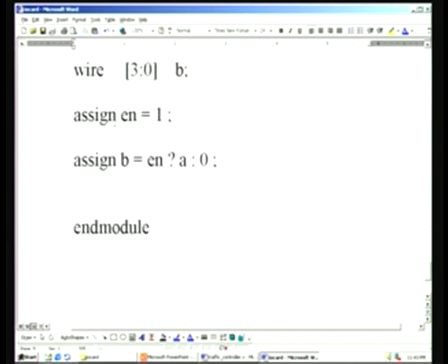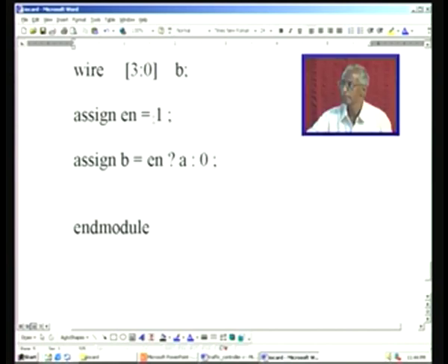So, for example, we enable first here, and in a concurrent statement there is another mux here. This is the output assigned: output B is derived either from the actual DIP switch which is connected to the input, or it is forced with 0. It is forced with 0 if enable is in disable mode, that is, enable is 0, naturally 0 will be forced onto B.